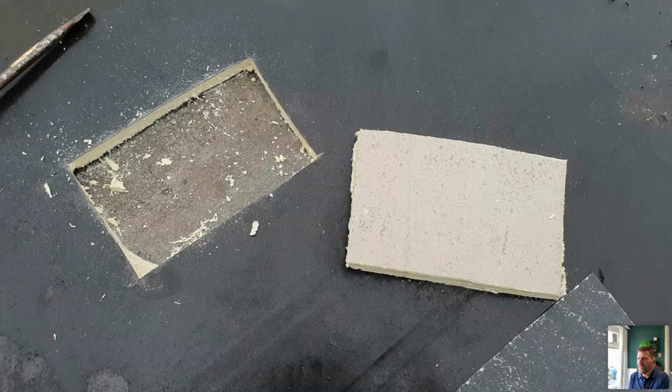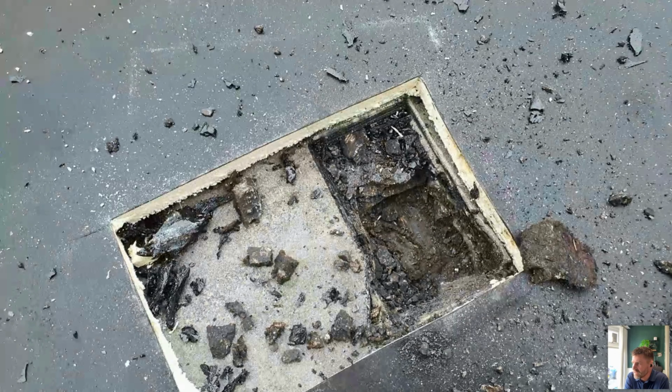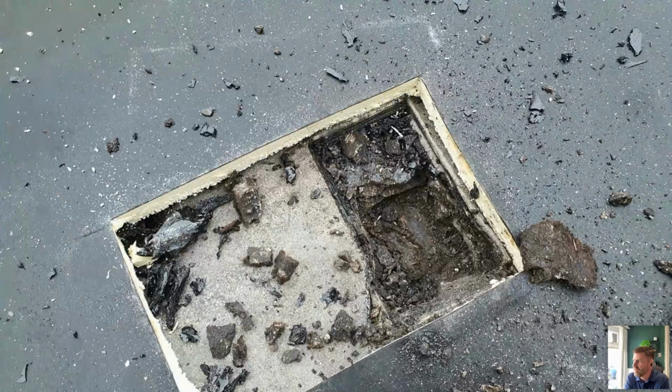So again, just a few examples I'm going to run through now with you. Maybe this one, to the untrained eye, might look like an EPDM single ply with some insulation on a concrete deck. But if we're destructively testing, we always need to scrape that concrete or whatever it is. When we've done that, we've actually found out that it's asphalt. So we obviously then need to establish what's beneath the asphalt. Is there more insulation in there? We're going to be doing U-value calculations, condensation risk analysis, everything like that.